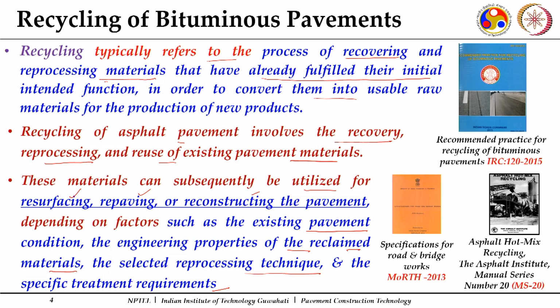For this, we have IRC 120 2015, which is the recommended practice for recycling of bituminous pavements. Along with it, many other codal specifications can be referred to, in addition to MoRTH 2013 specifications for road and bridge works. We have the Asphalt Institute Manual Series number 20 also on asphalt hot mix recycling.